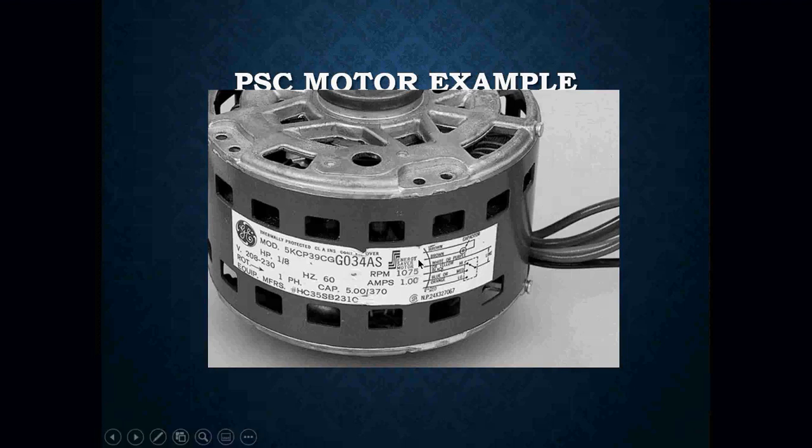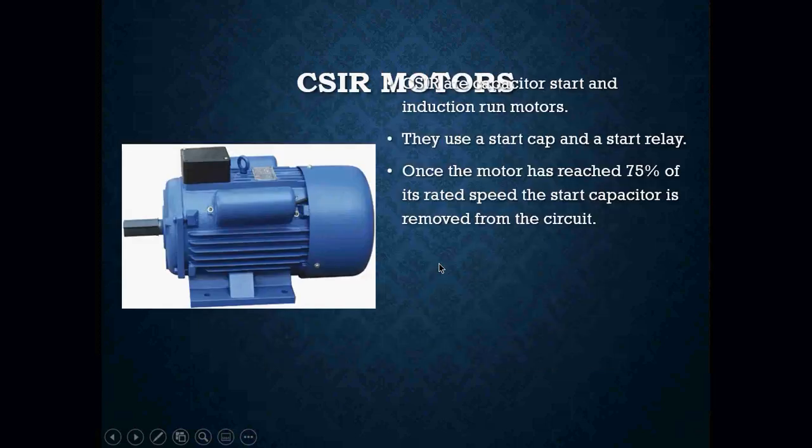In fact, if you look at the wiring diagram here, this looks like a multi-speed PSC motor. It looks like a red wire is low speed, a blue or orange wire is medium speed, and black is high speed. White or purple or yellow is my neutral, and then the 2 brown wires are for your capacitor.